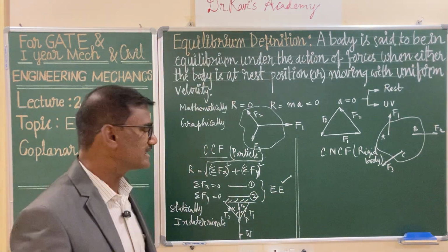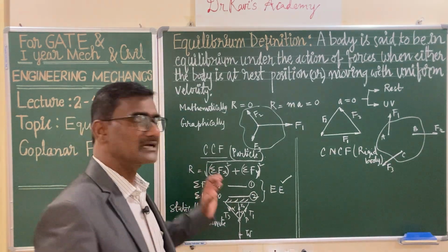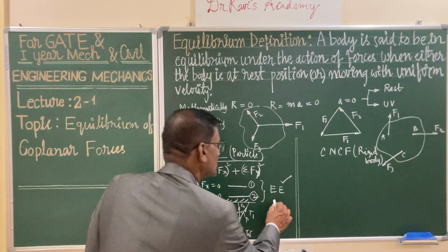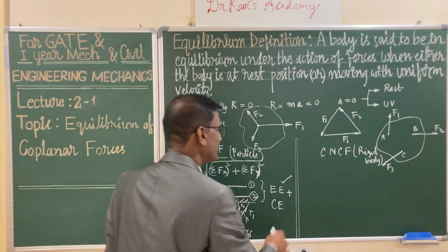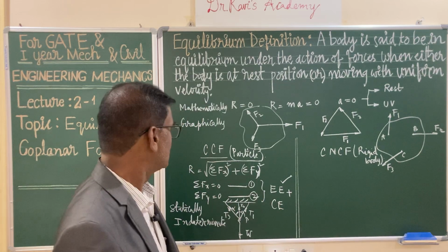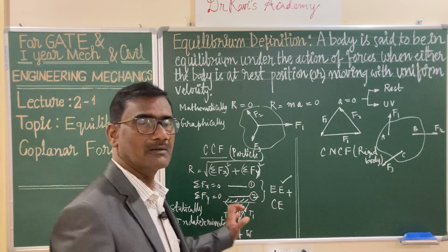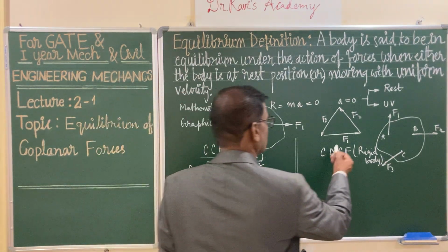What is required is that these problems will be solved in strength of materials by considering the geometry of the deformation, which is also known as a compatibility equation. We call it the compatibility equation. So equations of equilibrium plus compatibility equations will let you solve the statically indeterminate problem or system. The other side, let us look at coplanar non-concurrent forces.